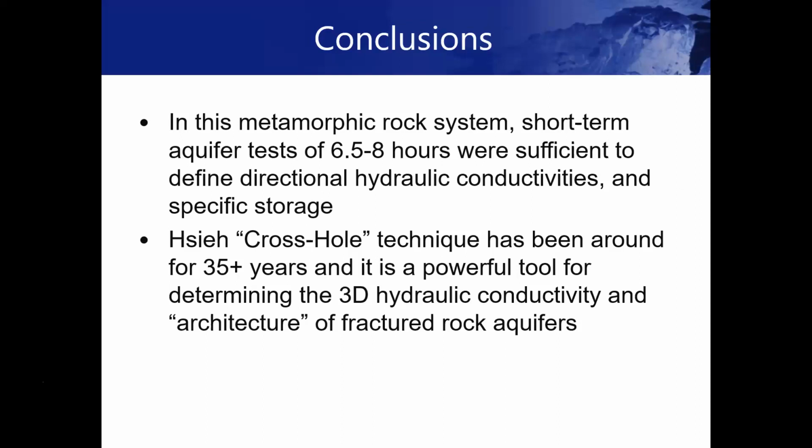So the Hsieh cross-hole technique, it's been around a long time, 35 years plus now. I've talked to Paul Hsieh about whether he's seeing a lot of application of this, and he's not. Nor am I. I do a lot of reviews of aquifer testing, because I taught it for years at Manhattan College and Columbia. I haven't seen anybody use it. I use it all the time. I think it's a really valuable technique for mapping hydraulic conductivity three-dimensionally. And I think we're only catching up to being able to model the results of all this data we get back from this.